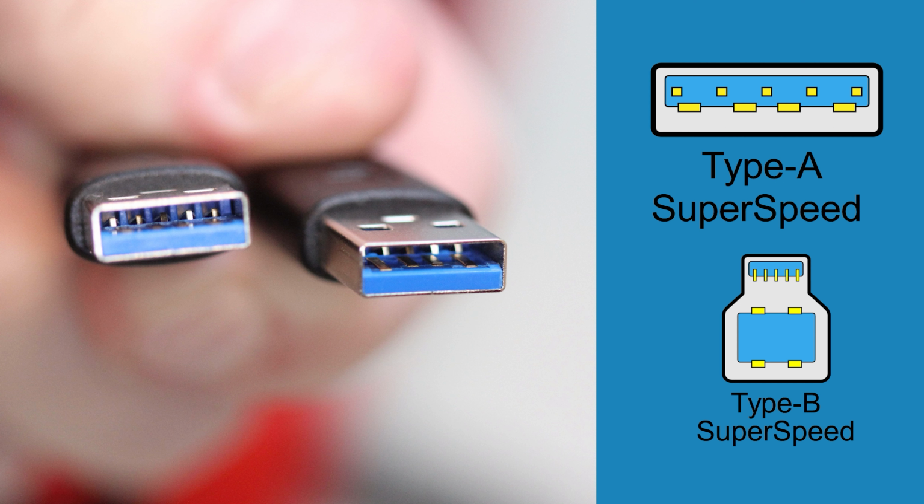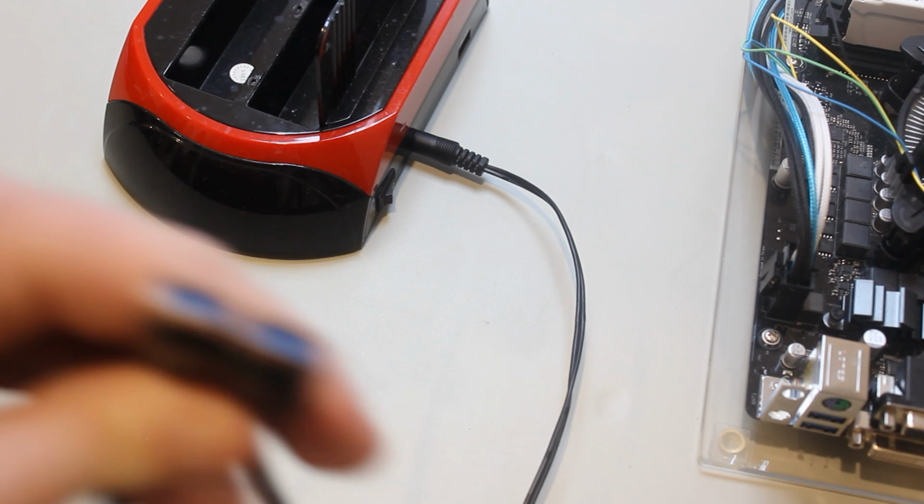A Type-A to Type-A cable that meets the USB 3 standard should have the power of the USB 2 wires disconnected. This is because if you connect two hosts together using USB 2, for example one computer to another computer, both will try to send power, which can cause problems. USB 3, by contrast, supports Type-A to Type-A cables and thus detects what is on the other end and won't send power in both directions. Personally, whenever possible, I would avoid purchasing devices with a Type-A connection. If you get a customer accidentally plugging two USB 2 hosts together, it is possible to cause some damage.